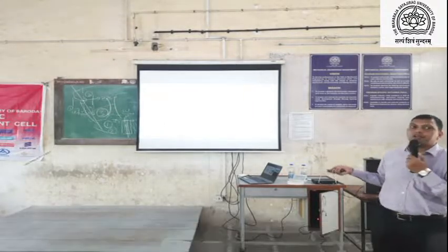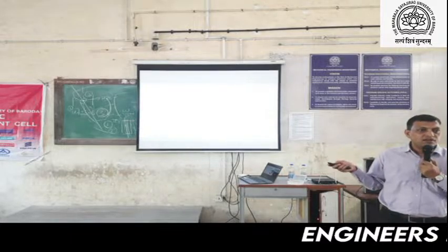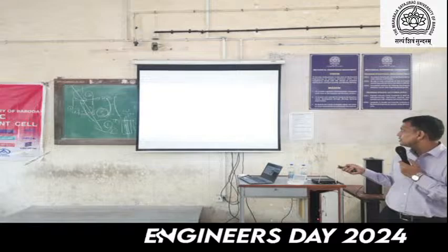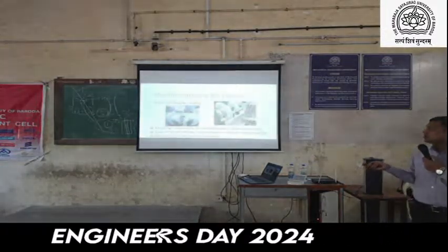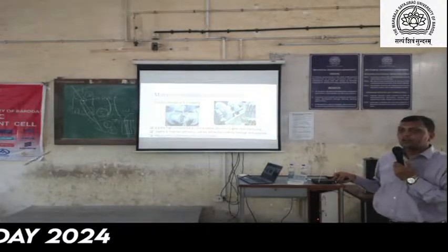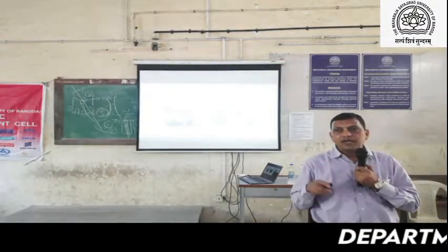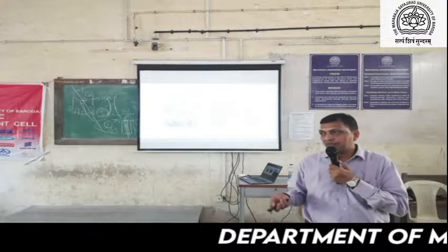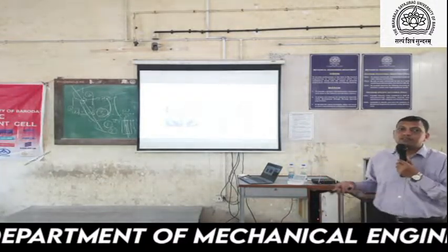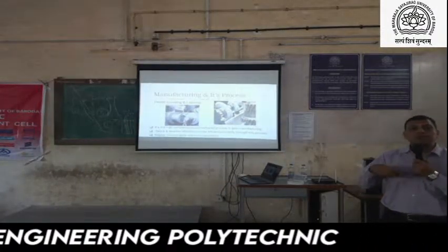We don't consider the tooth area in this portion. The tooth area requires a grinding operation. So why is grinding required? If we can do direct machining, we can apply this pinion application. But why do we require grinding? Basically, we can consider that it is to smoothen the surface.